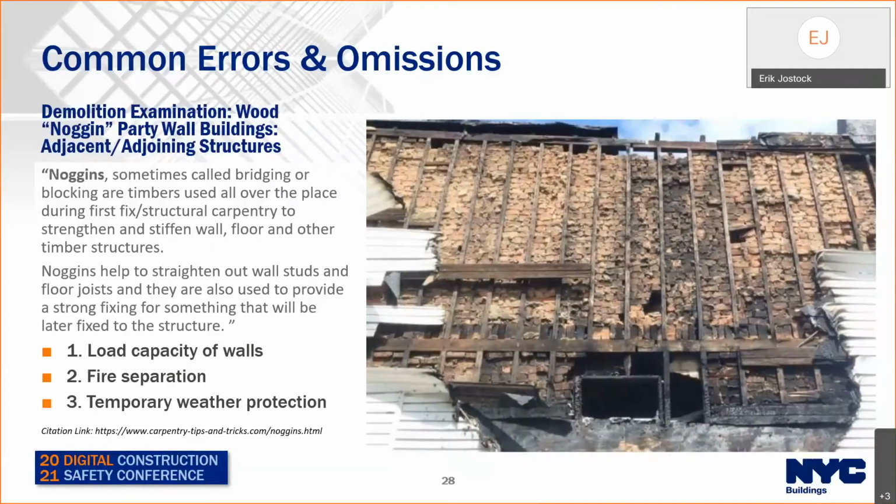This is an example of a condition that is rarely indicated on demolition plans that we receive. It's an unreinforced masonry infill for fire resistance. These don't turn up on plans until someone tries to sign one off, and we realize that it's not the CMU block wall that they showed on the plans. So this is commonly overlooked.